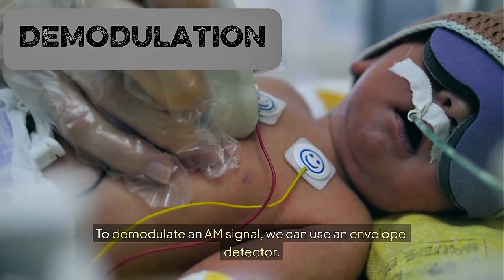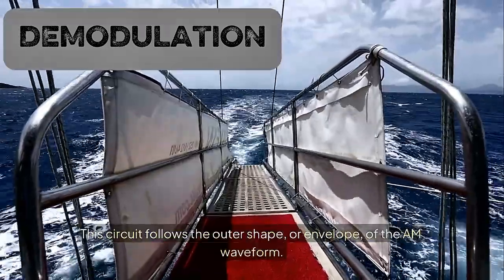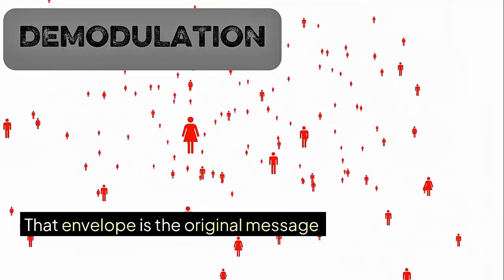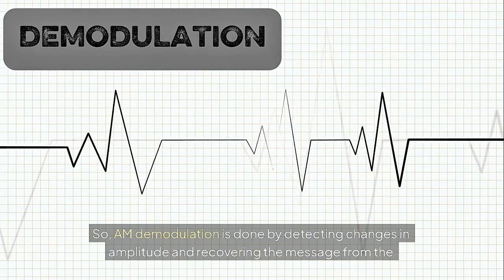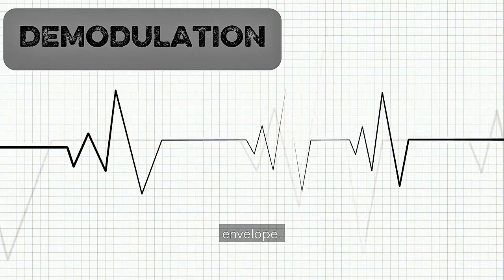To demodulate an AM signal, we can use an envelope detector. This circuit follows the outer shape, or envelope, of the AM waveform. That envelope is the original message signal. So, AM demodulation is done by detecting changes in amplitude and recovering the message from the envelope.